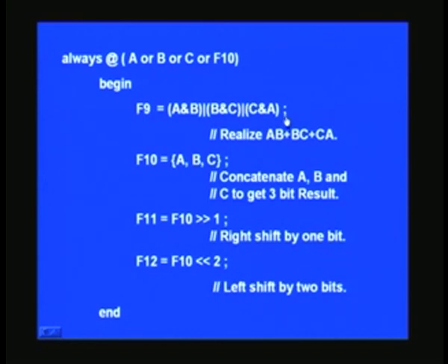If you forget this, the compiler will promptly report an error, and we will be learning all those gradually. Next example was concatenation, as we have already seen, and it is precisely what we have seen pictorially there. These flower brackets concatenate the A, B, C signals. Suppose you want C as MSB, you should put C here and then A comma B, in any order.